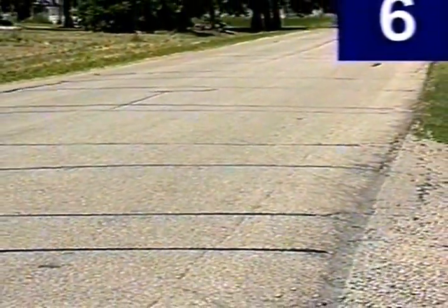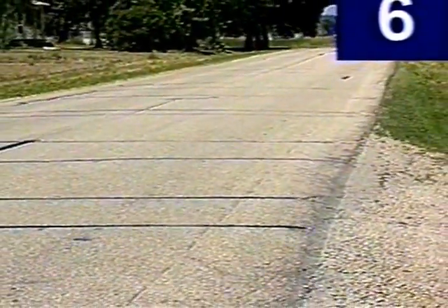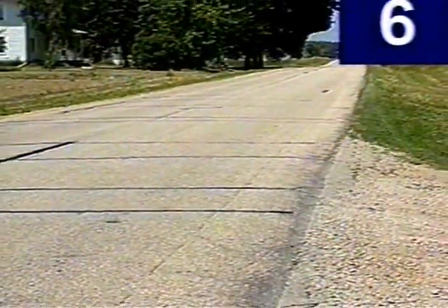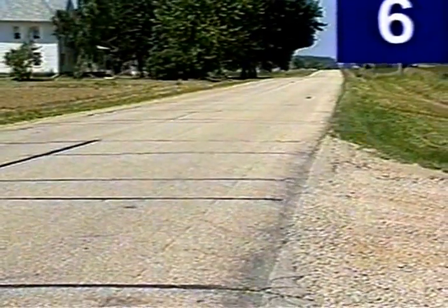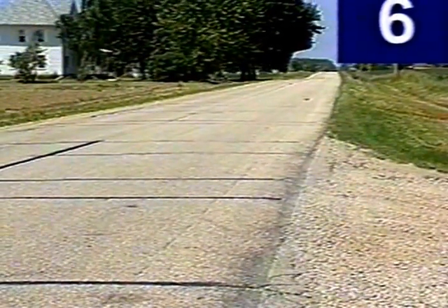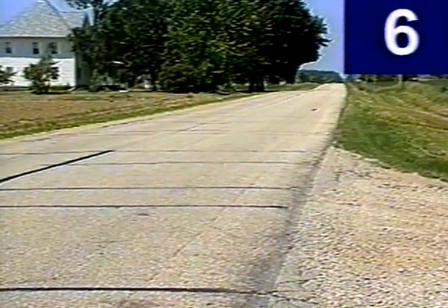Here's another pavement where the transverse cracking has continued to the extent that they're only a few feet apart now. Therefore, you're beyond just crack sealing. I think a preventative maintenance like a seal coat would be an excellent treatment for this pavement. You can see here the cracks are still hairline and enclosed.